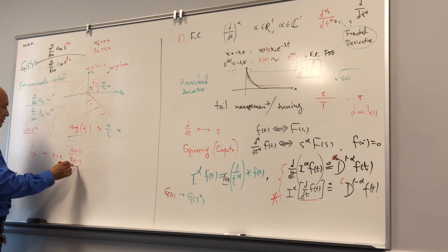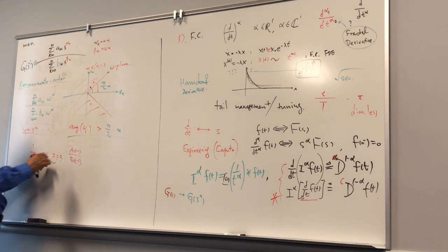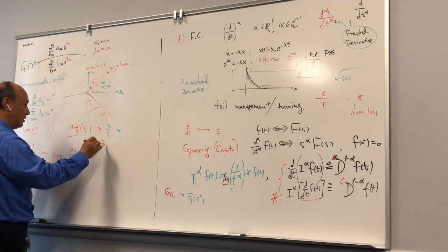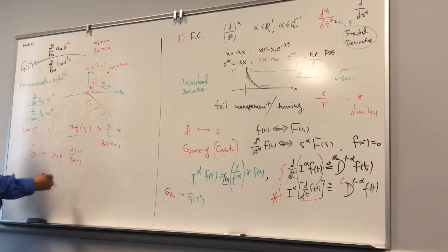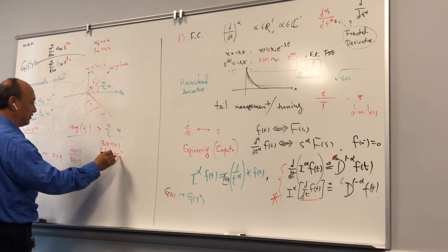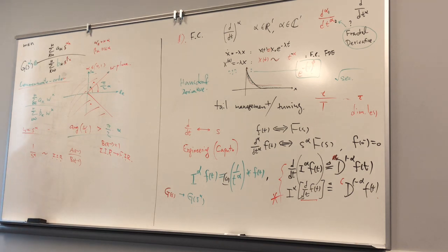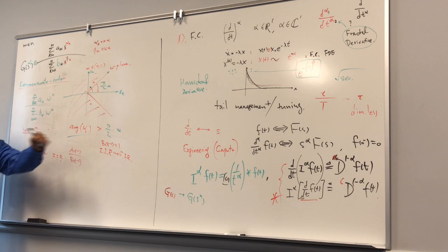These are polynomials of z^-1. If the B is 1, then this IIR becomes FIR, finite impulse response. So if you don't have a denominator, then this is an FIR, okay?